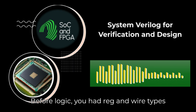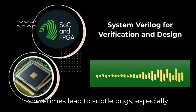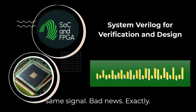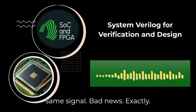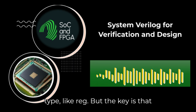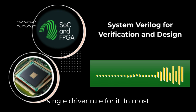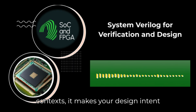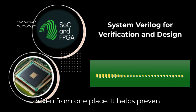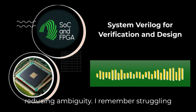Before logic, you had reg and wire types in Verilog, and the distinction could sometimes lead to subtle bugs, especially around multiple drivers. Multiple things trying to control the same signal. Bad news. Exactly. Logic simplifies this. It's a four-state type like reg, but the key is that synthesis tools generally enforce a single driver rule for it in most contexts. It makes your design intent clearer: this signal should only be driven from one place. It helps prevent those kinds of errors. So it's about reducing ambiguity.